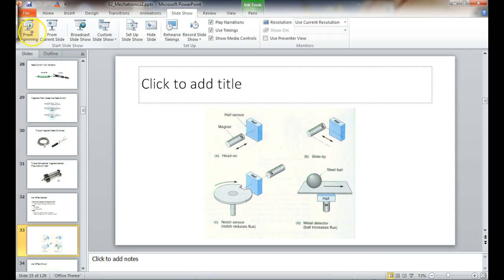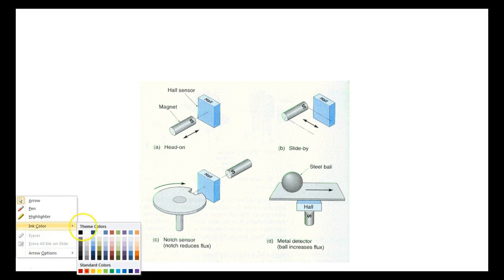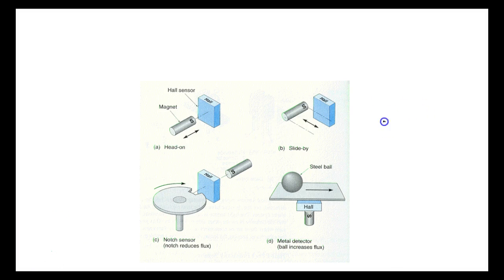So a 2-wire sensor usually simulates a normally open switch. I haven't seen one that comes normally closed, but I'm not going to say you're not going to run into it. But a 3-wire sensor would simulate a single pole, single throw switch, normally open. And then a 4-wire sensor would simulate a single pole, double throw switch.